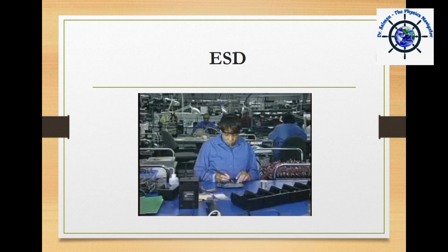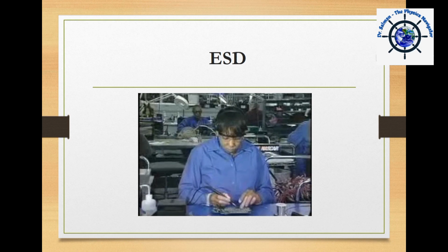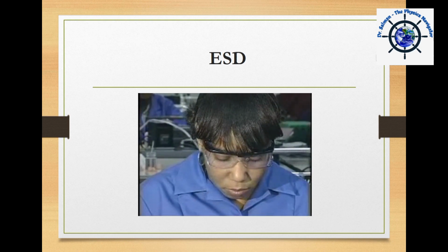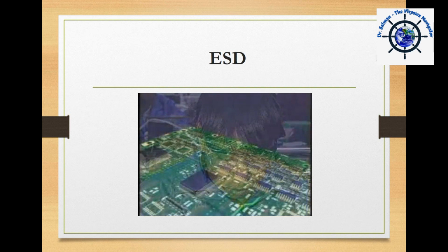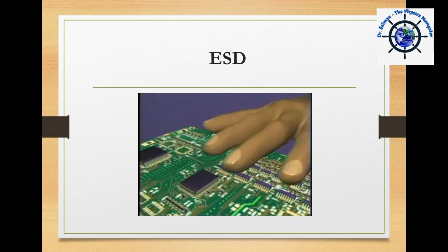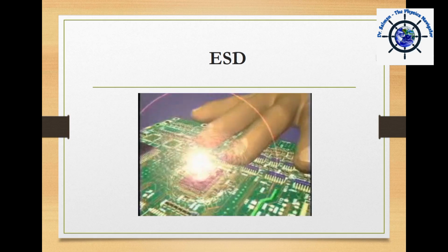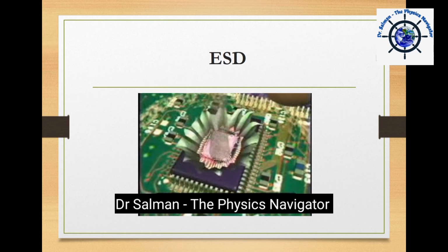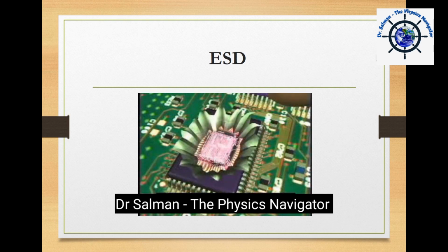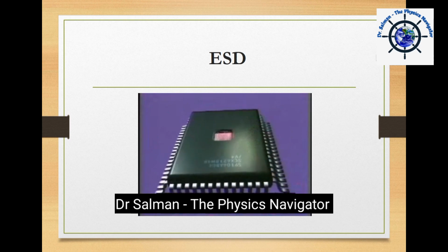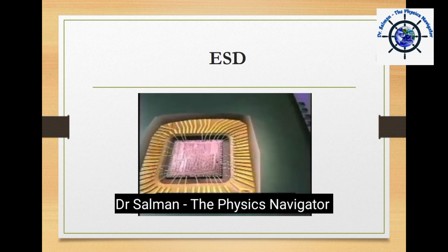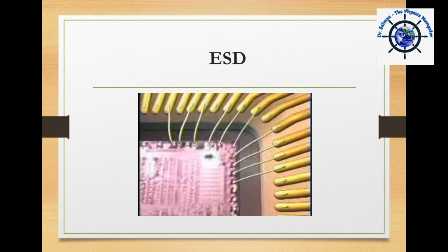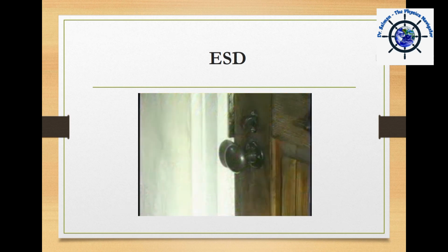People are the biggest cause of ESD. That's because our bodies easily pick up static electricity. In fact, our skin can store relatively large amounts of this electric charge. Doorknobs probably don't mind a spark, but when ESD passes through an electronic device, such as an integrated circuit, it can cause serious internal damage to that component, resulting in a scrapped component. The tiny circuit paths in these sensitive devices can be burned up or severed by an ESD voltage so small that our sense of touch can't even detect it.